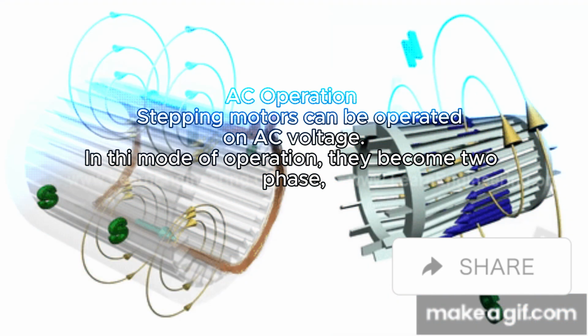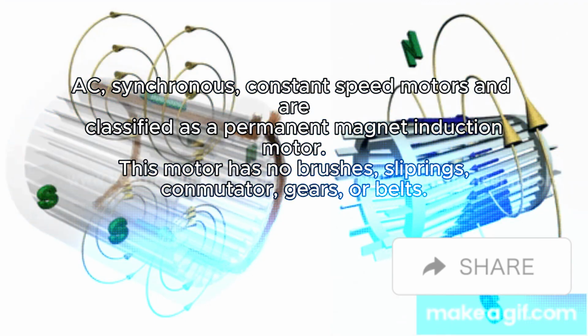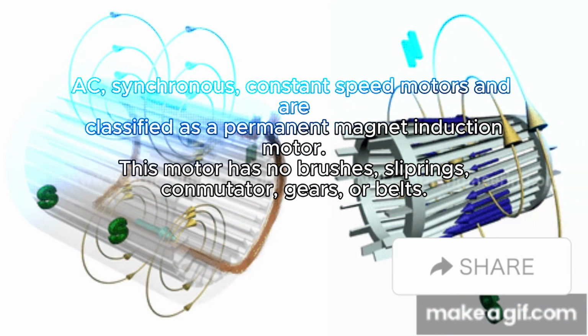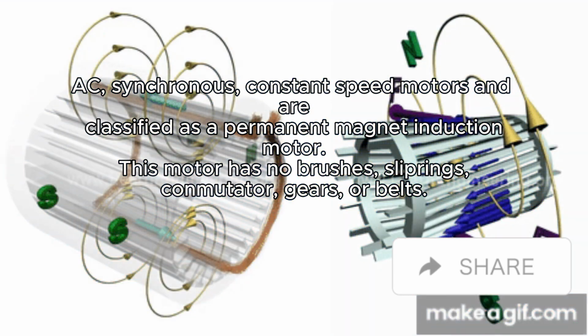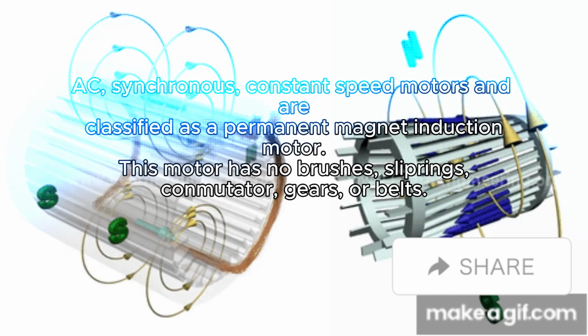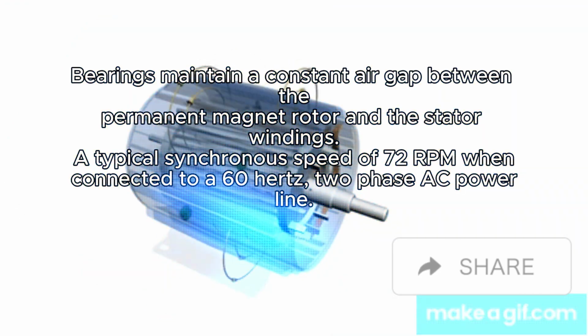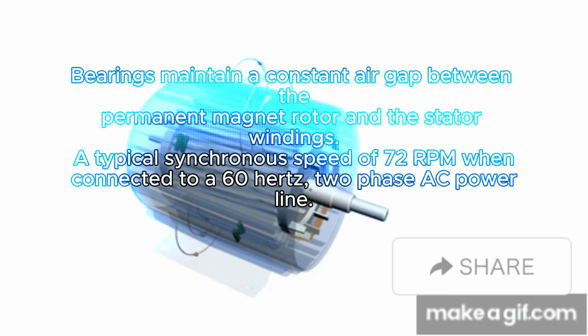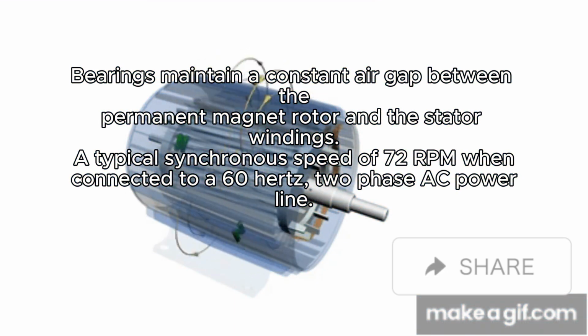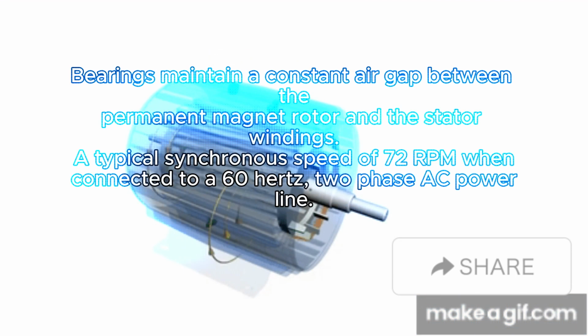In this mode of operation, they become two-phase AC synchronous, constant speed motors and are classified as a permanent magnet induction motor. This motor has no brushes, slip rings, commutator, gears, or belts. Bearings maintain a constant air gap between the permanent magnet rotor and the stator windings. A typical synchronous speed is 72 RPM when connected to a 60 Hz, two-phase AC power line.